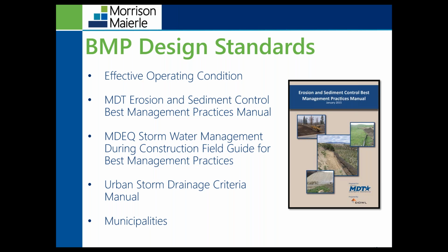And like I said, this is a way to make sure when you're performing your inspections, the administrator has to perform inspections to be compliant with DEQ on a weekly or bi-weekly frequency. So when they're going on inspection, they're going to be using these BMP standards to make sure that those BMPs that were installed originally are still in effective operating condition to prevent sediment from discharging from the site. So I have some photos here that I'm going to show you of BMPs that are no longer in effective operating condition. They're not preventing sediment from being discharged from the site.